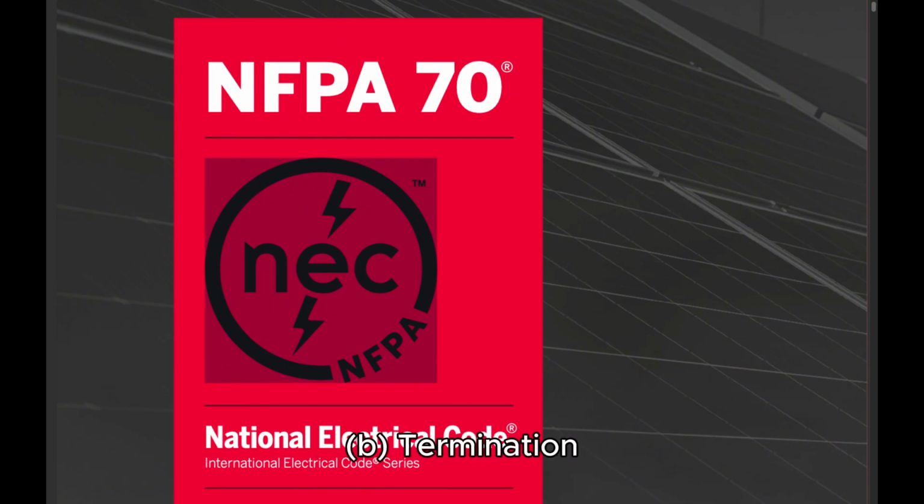2. Termination provisions of equipment for circuits rated over 100 amperes or marked for conductors larger than 1 AWG shall be used only for one of the following. 1, conductors rated 75°C (167°F). 2, conductors with higher temperature ratings, provided the ampacity of such conductors does not exceed the 75°C (167°F) ampacity of the conductor size used, or up to their ampacity if the equipment is listed and identified for use with such conductors. 3, separately installed pressure connectors shall be used with conductors at the ampacities not exceeding the ampacity at the listed and identified temperature rating of the connector.